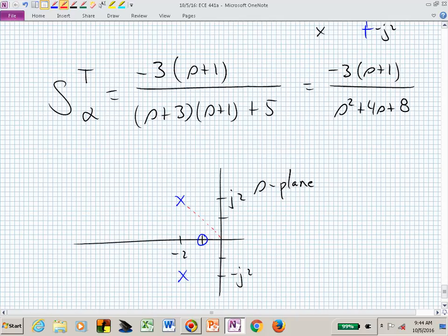It's a right triangle with equal sides, isn't it? So we now have the side times the square root of 2, so that's 2 times the square root of 2. This is our natural frequency. Omega sub n is 2 square root of 2, about 2.8. It's about 3 away from the origin. And it has a real part of -2 and a damped frequency of 2. So it will now be an e to the -2.